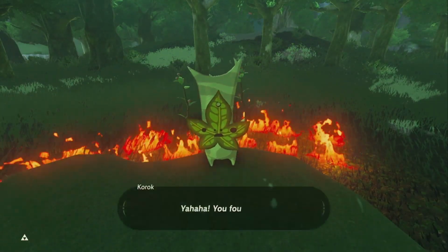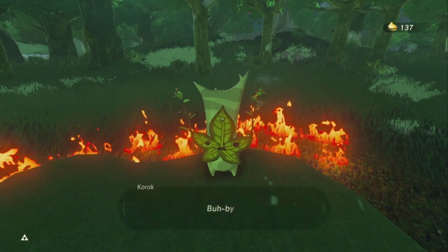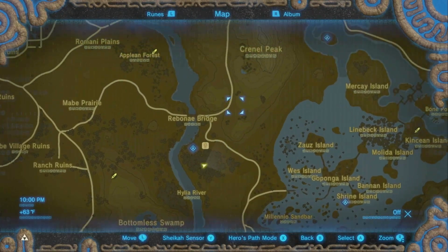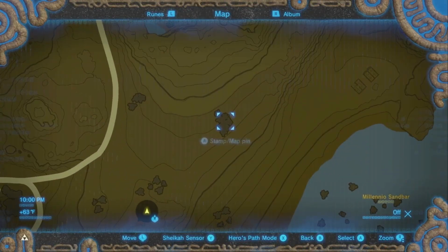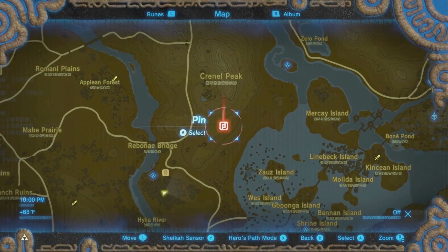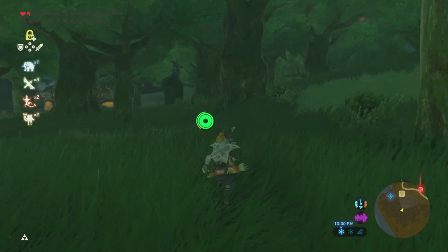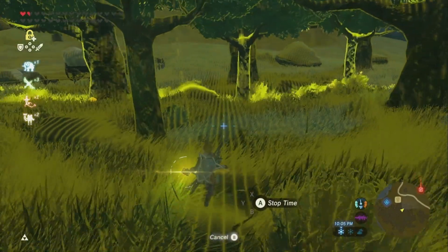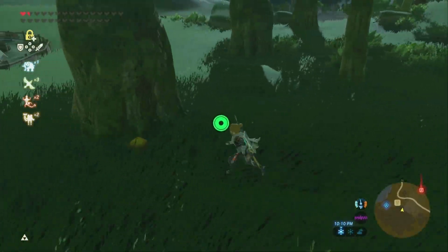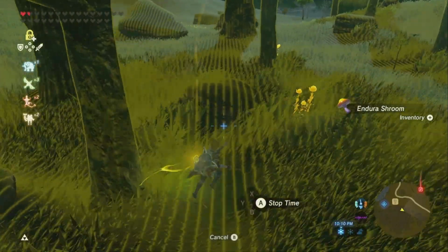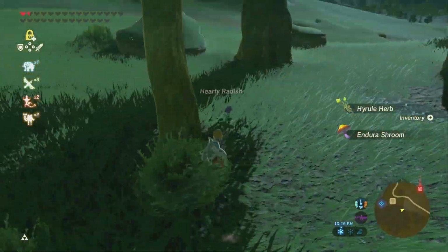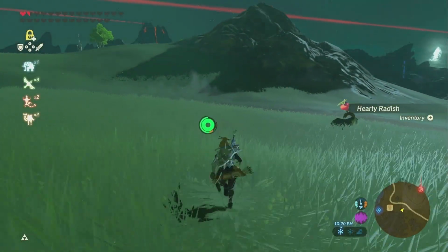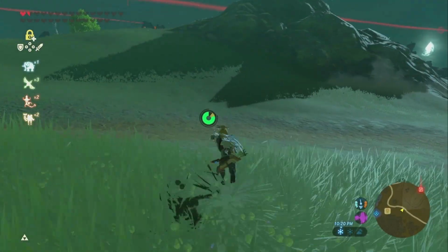Gas burner cover and rollout shield. Check to see that the burner cover and heat rollout shield are both present and in good condition. A rusted cover sheet may indicate leakage or condensation. Gas burner cover missing, damaged, or rusted. On gas water heaters, the burner is typically concealed behind a door and a flame rollout shield. You'll want to open the door and move the flame rollout shield during your inspection to get a look at the burner in operation and at rest.